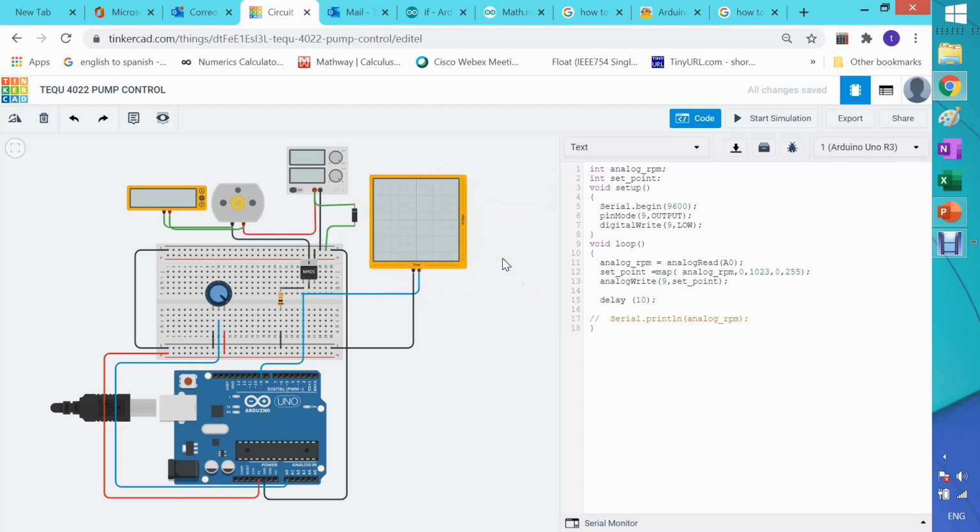And you will see that analogWrite fires about 5 times within 10 milliseconds. That would be about 500 hertz, which is what the Arduino literature says for pin 9, if I got that right. I can certainly check that.